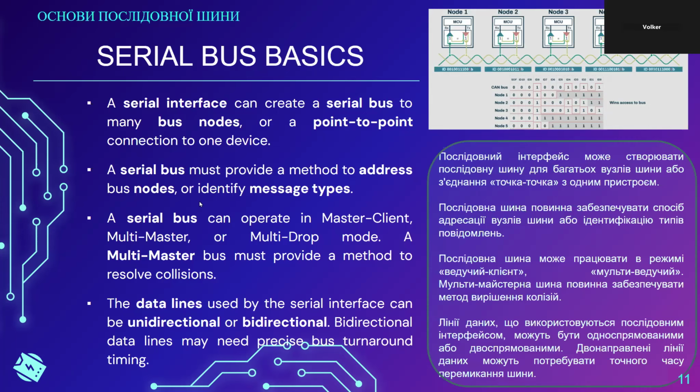The CAN bus was originally designed, and we're going to talk about that later, in an automotive environment as a broadcast bus. And every device sitting on the bus was supposed to listen in to specific messages and then filter out what kind of message was important to it.